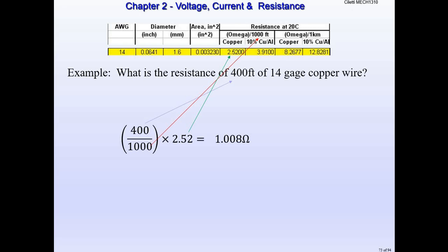Okay, this is really big in transmission lines, long electrical lines that go like 100 miles before they have to reach a substation, because when you're doing thousands of feet of wire, there's going to be a large amount of resistance over certain distances. So if we look from 1,000 feet, a mile is 5,280 feet. Roughly, if we take 2.52 times 5, you're going almost at 12 ohms of resistance every mile. All right, 100 miles, that's going to add up quickly, 1,200 ohms. So what's going to happen when we have that resistance? You won't get as much current and your electricity won't be as efficient.